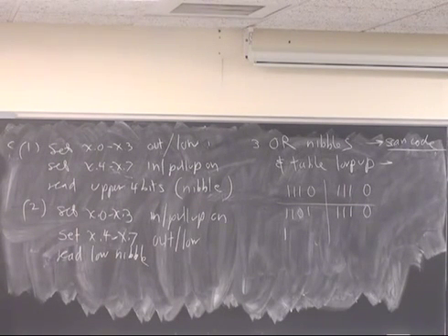So the question is, if you had multiple button pushes, could you actually detect them and discriminate them? And the answer is sometimes. It depends on whether they're in the same row or the same column. But yes, you can make a shift key to double the number of functions, go to 32 buttons.